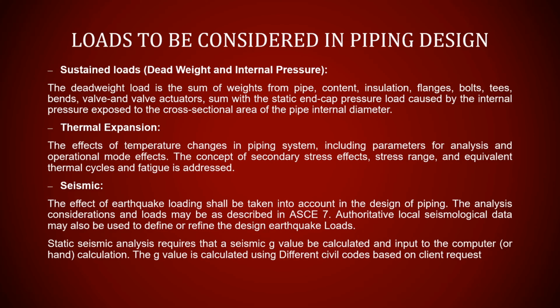Seismic. The effect, based on the ASME B31.3, this was the paragraph mentioned in it. The effect of the earthquake loading shall be taken into account in the design of the piping. This analysis consideration and loads may be as described in ASCE 7-10.